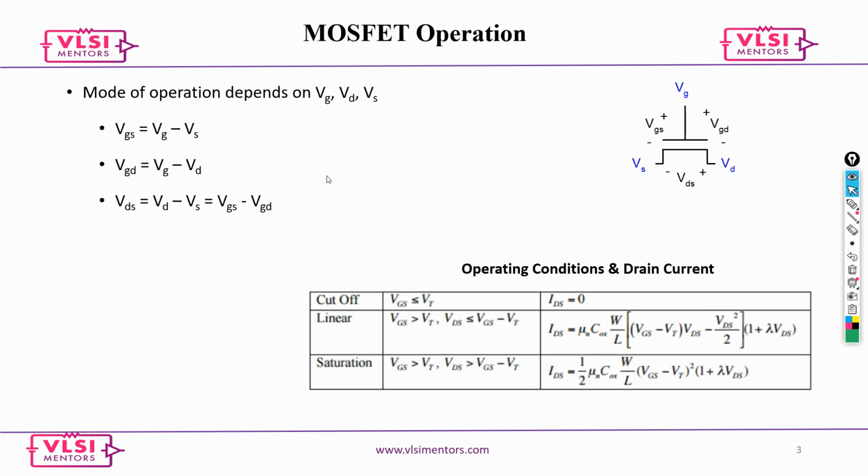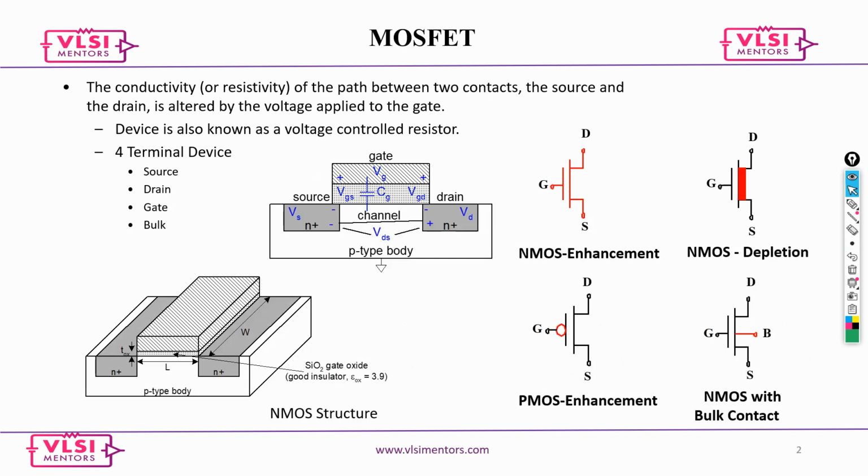Can I ask a question, sir? Go ahead. So that propagation delay will only depend upon the width to L ratio, or are there any other components like capacitances? At the transistor level, it depends only on these two things. But remember, your delay again depends on your threshold voltage and then temperature. There are many other things as well, but if you look at your individual transistor level, only the two things define the whole properties. They play a major role. That's the basic thing.